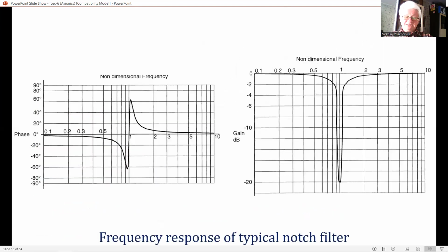The carriage of external stores and the fuel state produce significant changes in the modal frequency and must be taken into account in the notch filter and FCS loop gain.